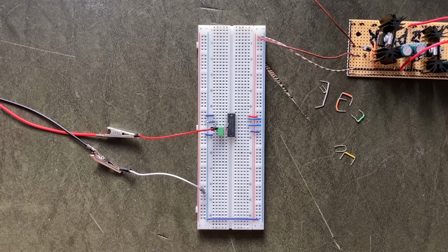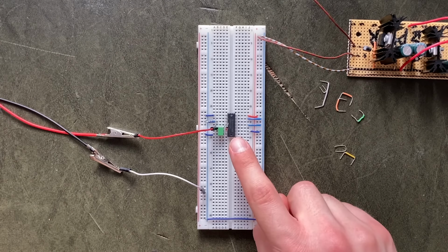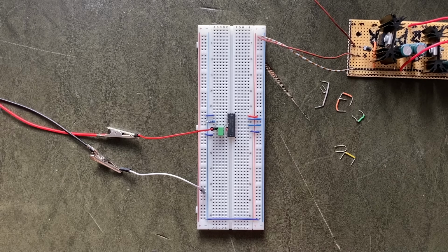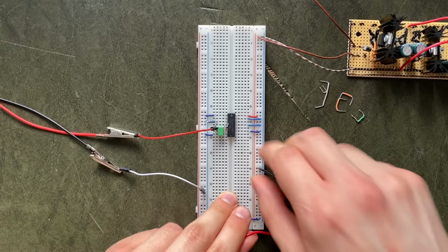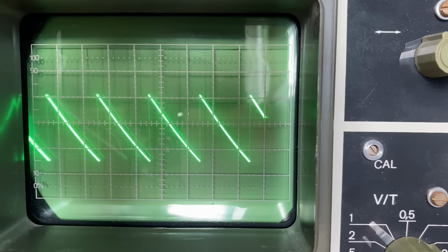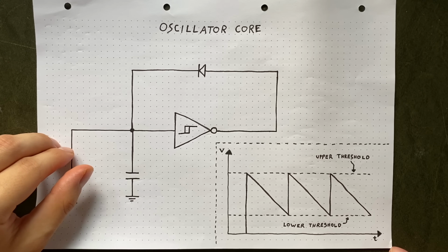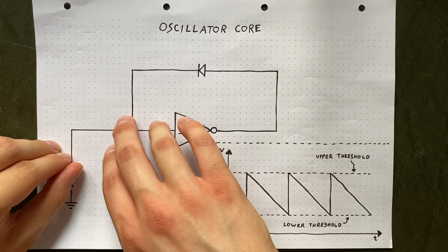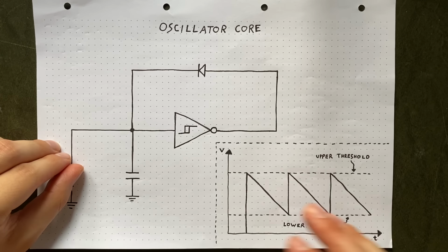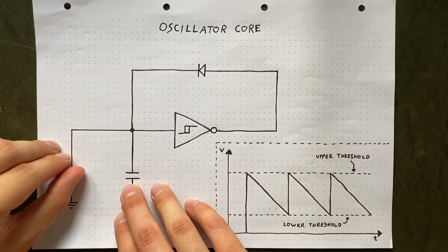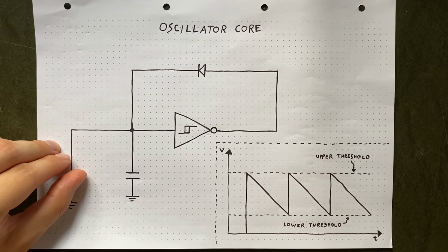You might be tempted to just attach an audio jack socket right where we plugged our oscilloscope in. Generally, that's going in the right direction, but sadly, it won't work at all. Let me demonstrate. The wave just disappears. And that actually makes a lot of sense, because what we're effectively doing is providing an additional path for our proverbial water to flow into. That way our capacitor is never being charged, because all of the current is leaving through our audio jack.